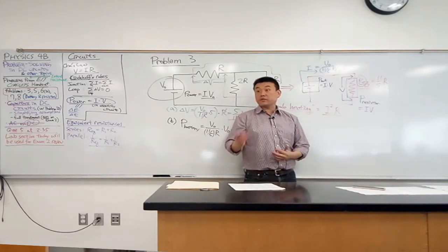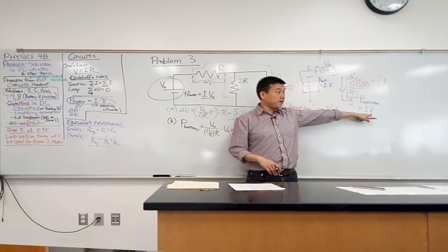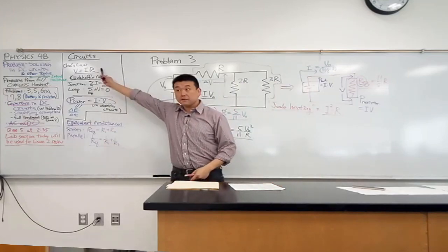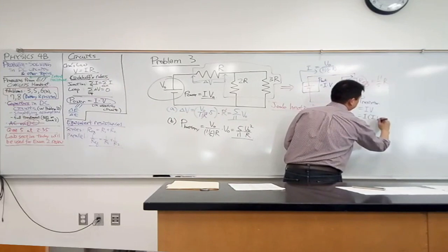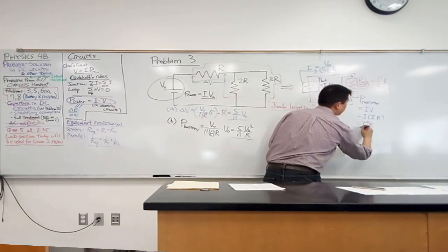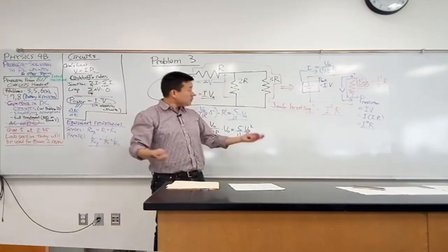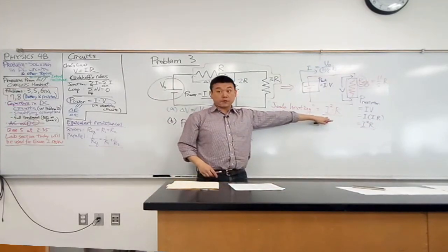because I still have to talk about the current that's flowing through it. So I rewrite V in terms of resistance and current using Ohm's law. Then V is equal to IR. So with that, this becomes I squared R. So that's where this formula for Joule heating comes from.